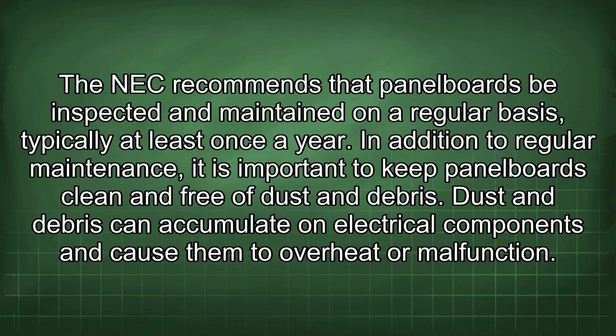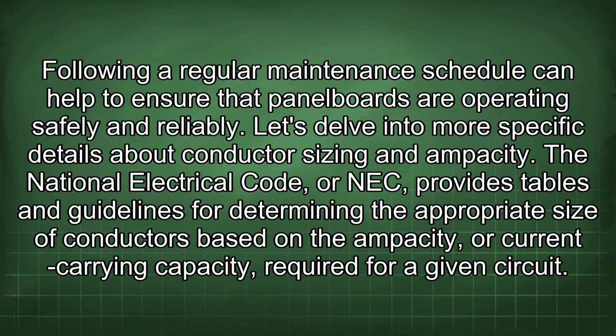In addition to regular maintenance, it is important to keep panel boards clean and free of dust and debris. Dust and debris can accumulate on electrical components and cause them to overheat or malfunction. Following a regular maintenance schedule can help to ensure that panel boards are operating safely and reliably.